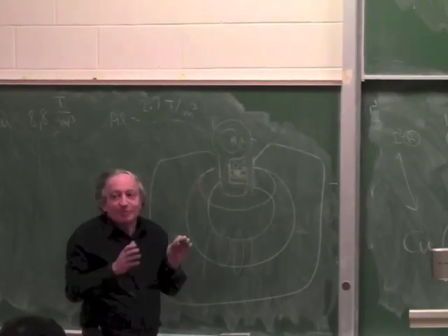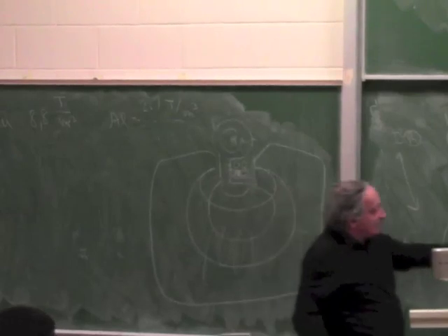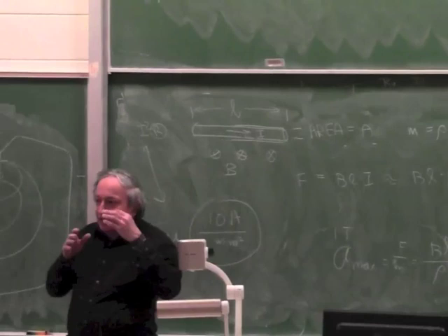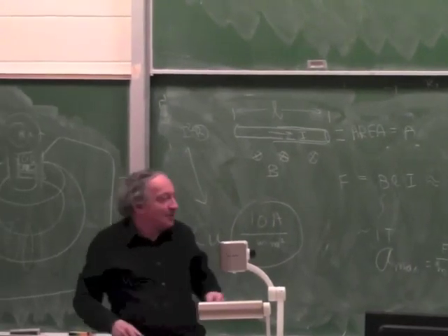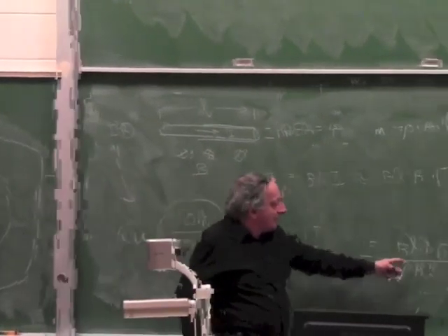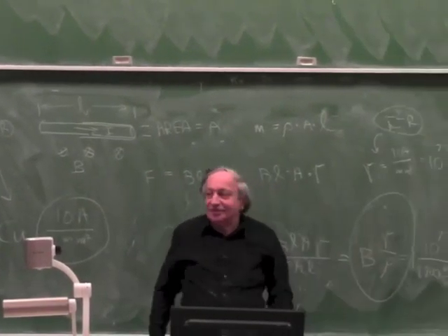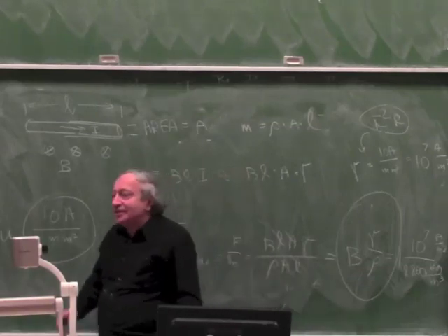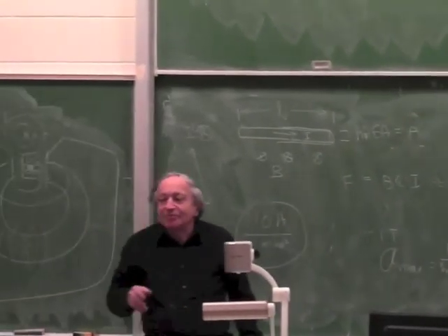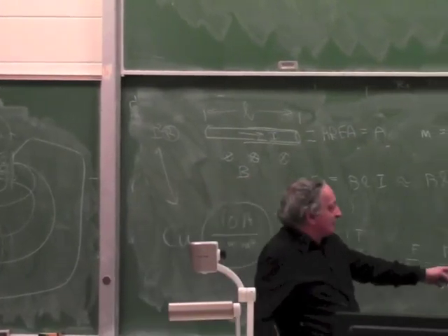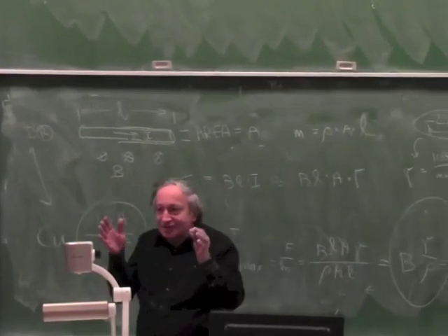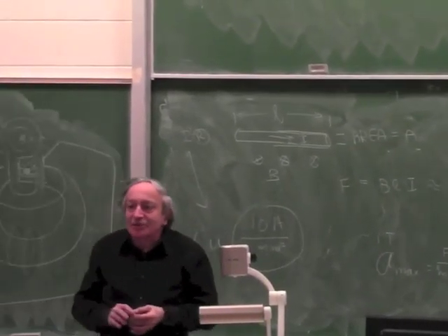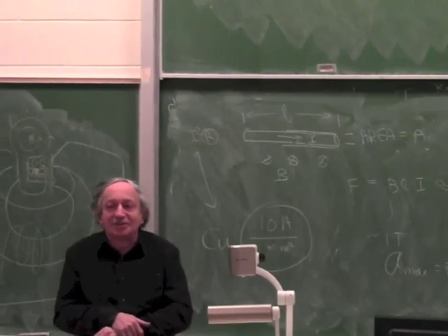And if you make the gap a bit bigger, B goes down a little bit. I won't take you through the whole optimization, but you can envision it, right? Because if B goes down a little bit, it cancels some of the gain. The ratio of current density to physical density, let's say, is 1.6 or 2, but you have to discount another 10% because B will drop a little bit, because you have to increase the gap. Anyway, you can go through this whole calculation. I won't bother you with it. So the bottom line, it's still at least 30% better.